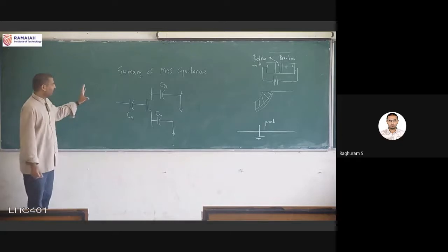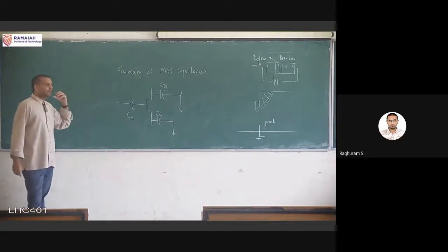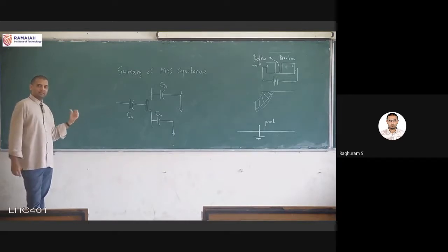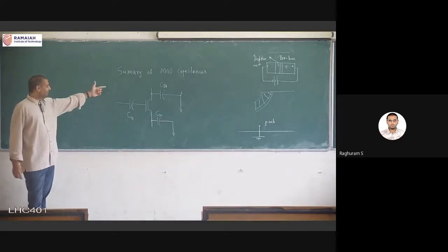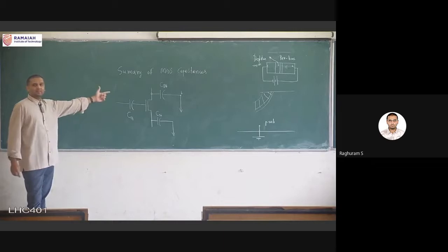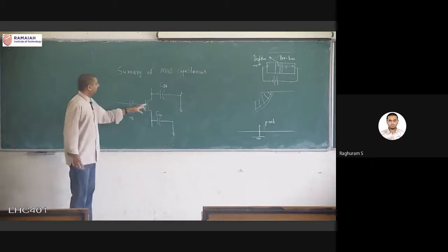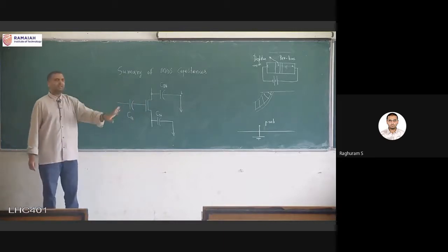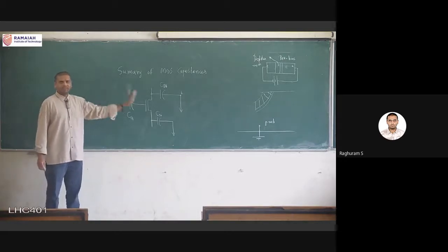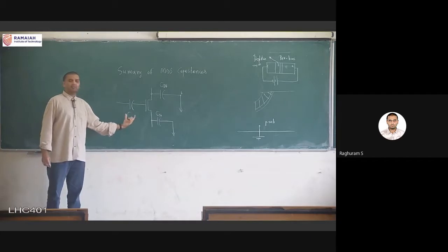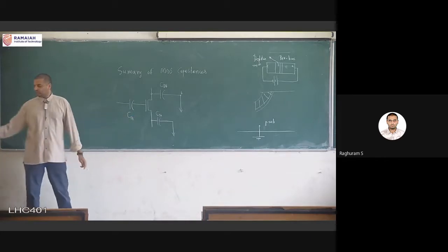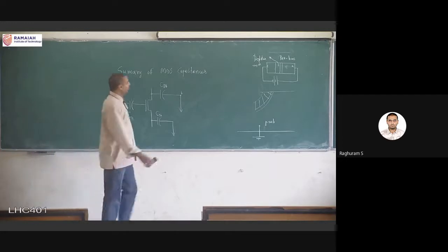So this diagram is very important. Every MOS transistor is associated with three terminal capacitances. One is associated with the gate terminal, and the other two are associated with the diffusion terminal, CSB and CDB. And for the gate terminal, the other capacitance depends on the region. We don't have to worry about all that. We have done the detailed analysis. We only know that some particular value will be there at the gate terminal. So this is for an NMOS transistor. I will also draw it for a PMOS transistor.